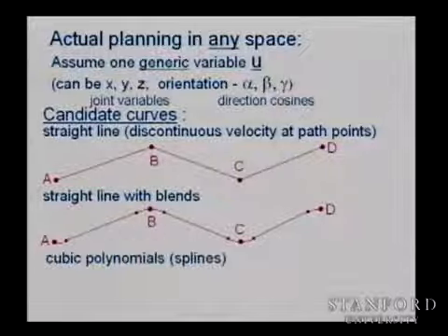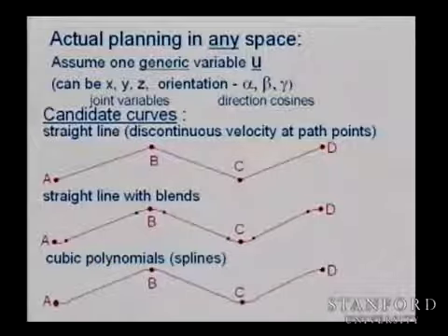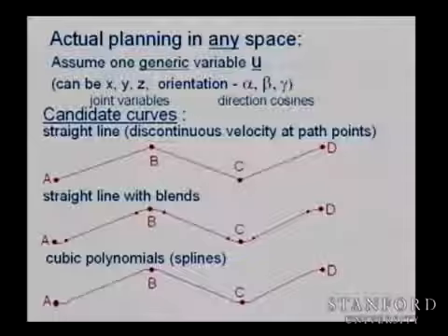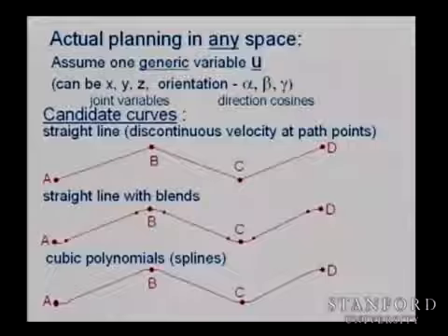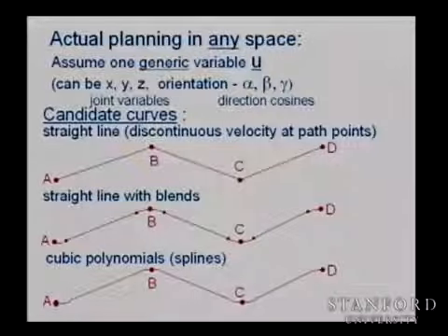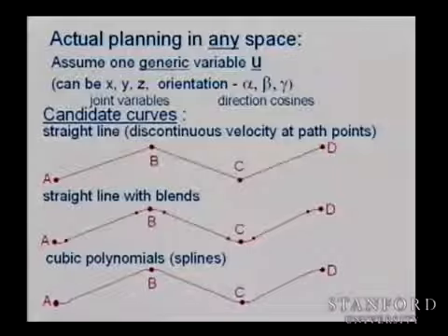And then, of course, another way to do it is, instead of using straight lines, we can actually use a cubic polynomial. The example here almost looks like a straight line with blends, but think of it as a cubic polynomial, right? So you're actually having a higher degree of freedom curve between each of the points along the path, okay? That will be slightly more complicated from a formula point of view. So everybody following? It's pretty simple, but...